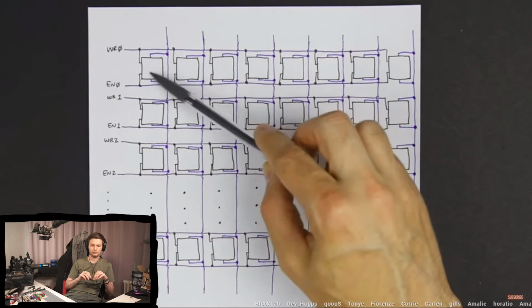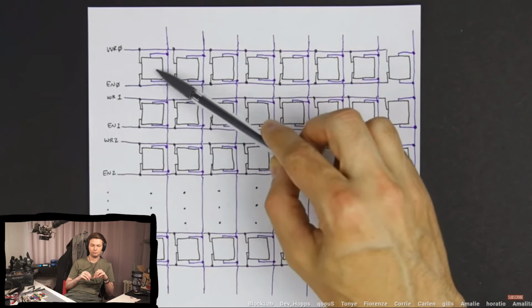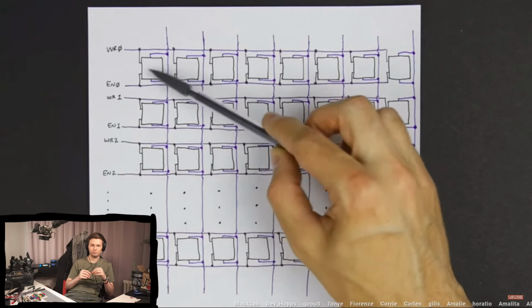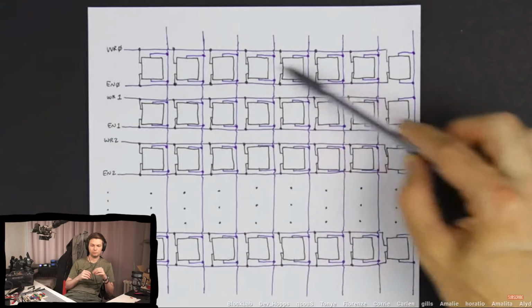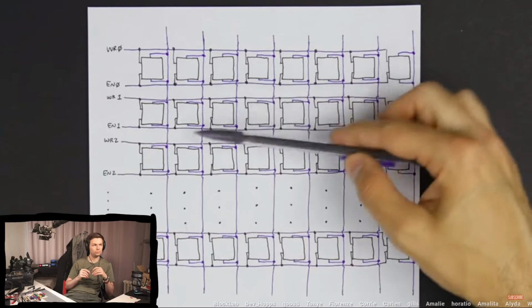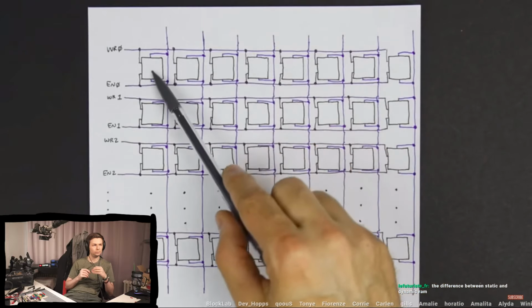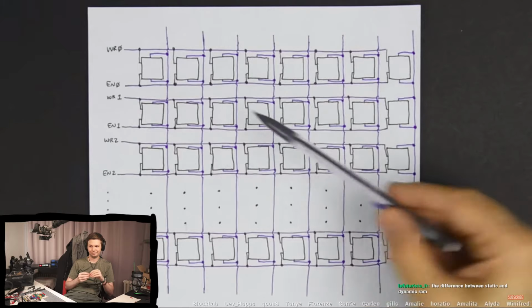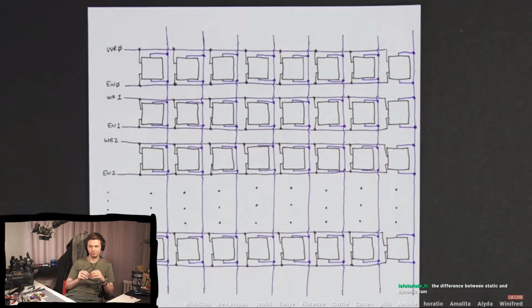So even though a capacitor could only store that data for at most a couple seconds, because we're reading and writing that many times a second, it's keeping that data refreshed. But because we have to continually refresh it like that, this is referred to as dynamic RAM. It's dynamic because if you don't refresh it, you lose the data that's in it.